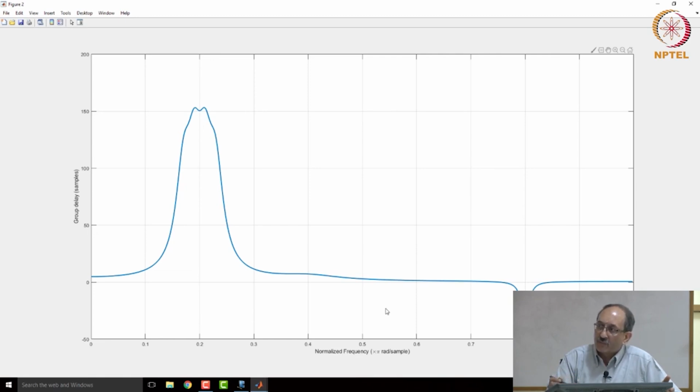It so happens that the first pulse frequency location is such that it is around that area of frequency. Its frequency content is exactly where you have the sharpest change in phase, and therefore, the largest group delay, and this group delay is manifesting itself as that component appearing 150 samples later at the output. So, this is why it is called group delay, all right, and hence you see in this example dramatically the order of the two pulses gets reversed.